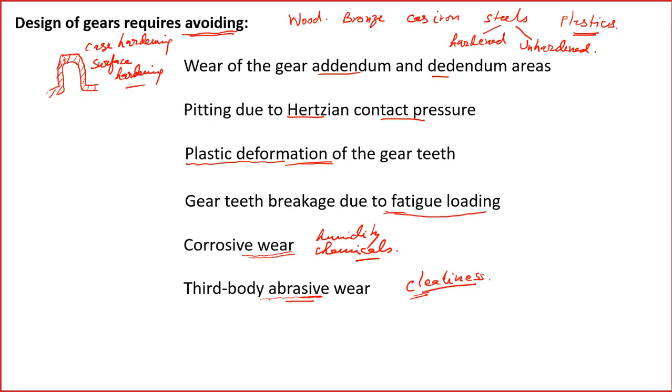In this case, the hardness is increased for some distance starting from the surface, maybe a couple of millimeters, and it is extremely hard, HRC in the range of 60 Rockwell hardness, whereas inside, the core hardness will be in the range of 40. So this is the hardness of the case, this is the hardness of the core.